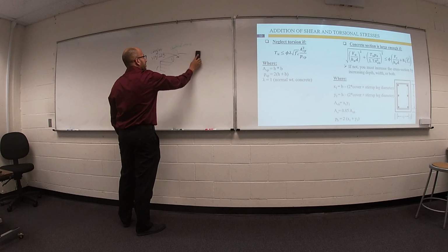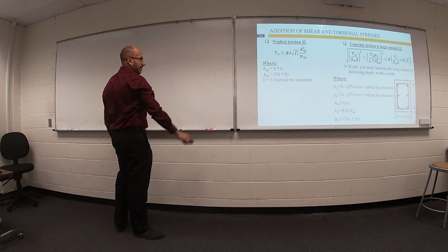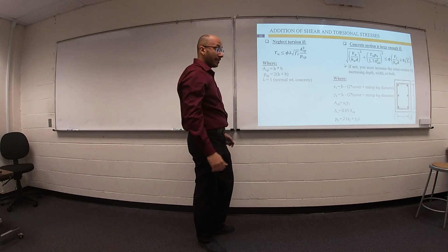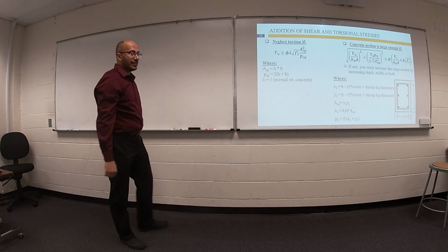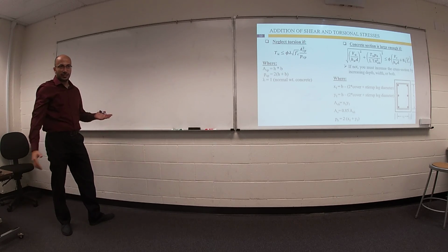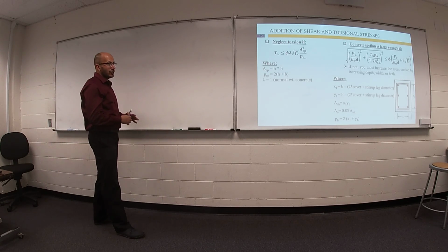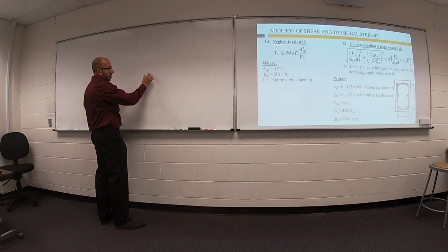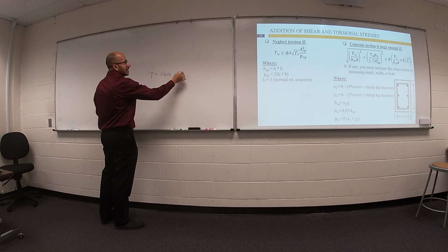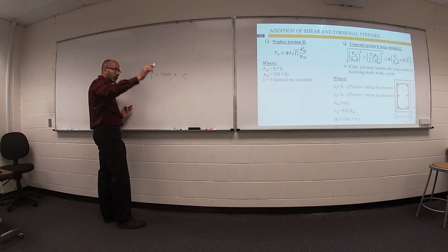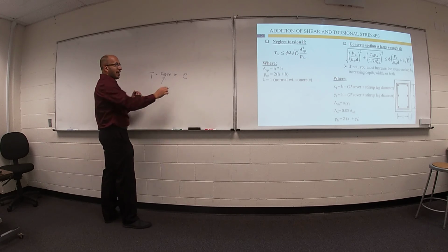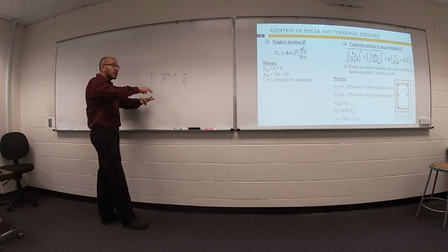One more question: being in California, maybe you account for that more, and here in Texas, other places? Yes, it depends on whether you have seismic activity in your area. So we have two parameters right now. Your torsion will be force and eccentricity. What is the value of your force based on your location? Then what is the eccentricity based on your distribution?